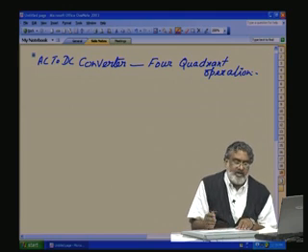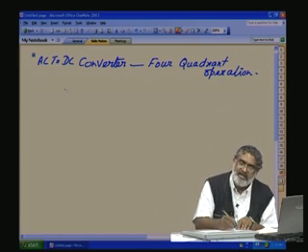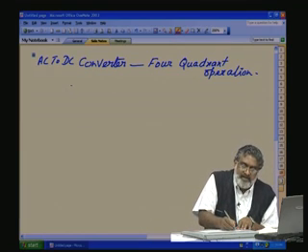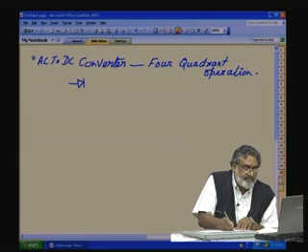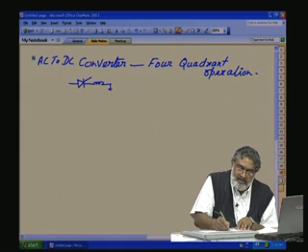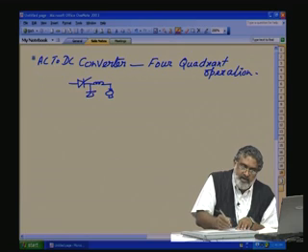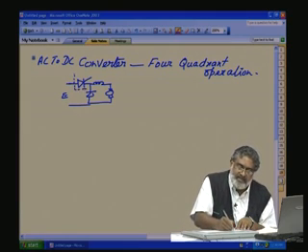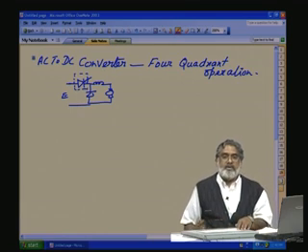Okay, we talked about our basic DC to DC converter previously, that is the buck converter. The configuration is like this. You have this one, then the inductance, you have the load, freewheeling diode D here. Okay. This is our E. Now, we are not showing the commutation circuit. Commutation circuit is inside, it is there. Okay.